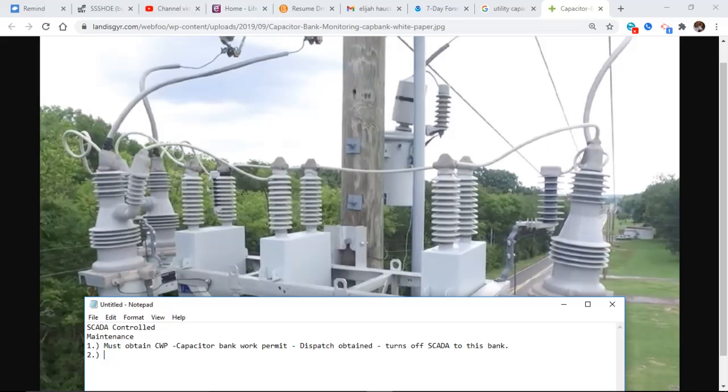Do we want to open up these switches with the capacitor bank closed and energized? No, you don't. All right. Is it some sort of load make? It is a load make, load break device. Good observation right there. We also don't want to open these switches under any type of capacitance load.